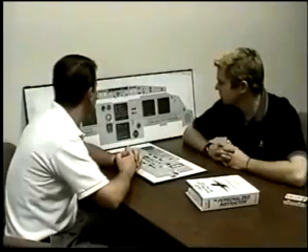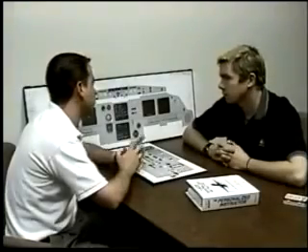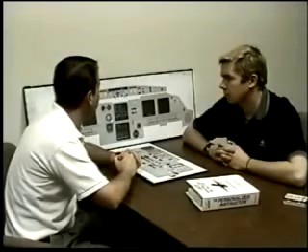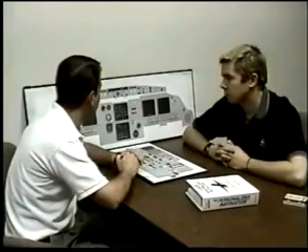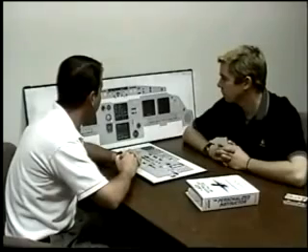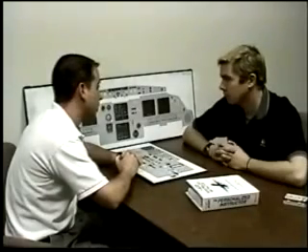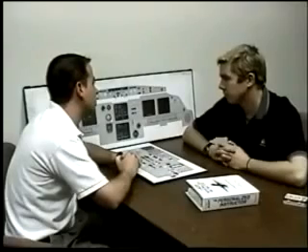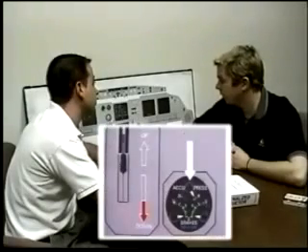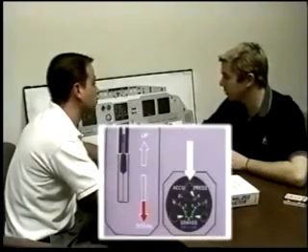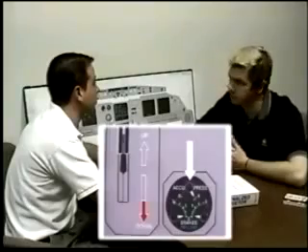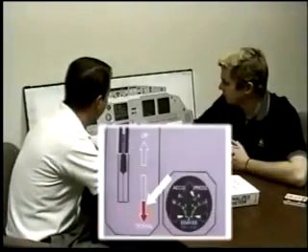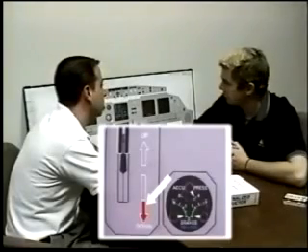Since we can't detect brake pressure being applied in normal brakes, it's going to force us into alternate brakes without anti-skid because of loss of the BSCUs. Right. What is your anti-skid detection now? It's basically your first officer's eyes on the brake triple gauge, making sure that he doesn't have in excess of 1,000 psi.